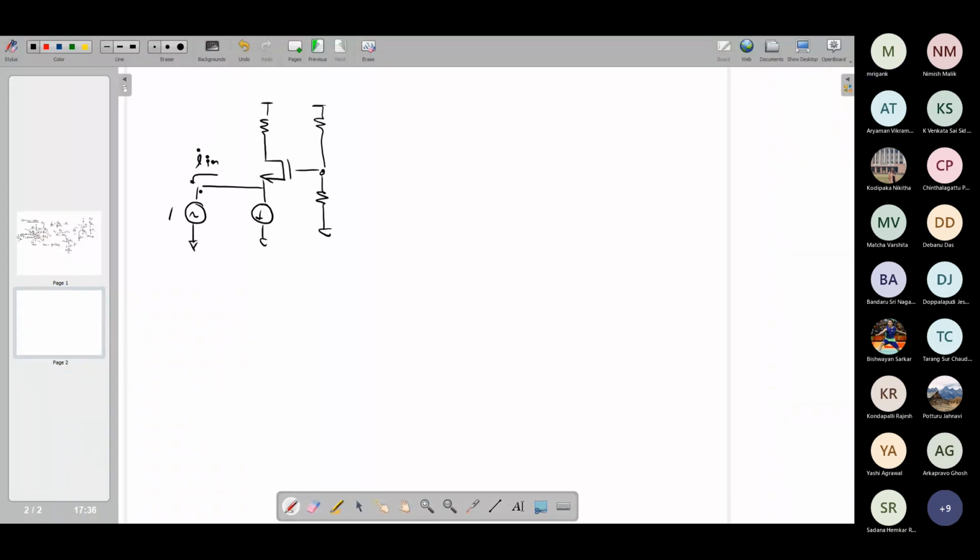I in. Now in this case, once again, if you assume that this bias current is ideal, what is the gain? What is the output signal? This is even simpler. If the source is non-ideal and also has R signal, then for a current source, how do we model the source resistance? It comes in parallel. So you need to take into account the R in of the circuit, which we have already found out. That depends upon whether RD is much greater or much lower than RO. So suppose we have that R in.